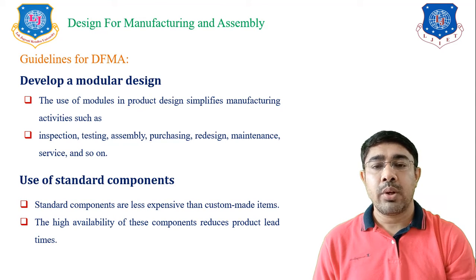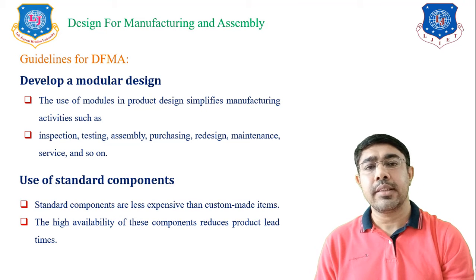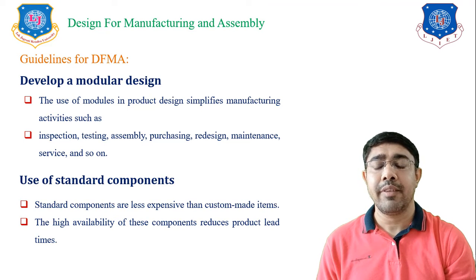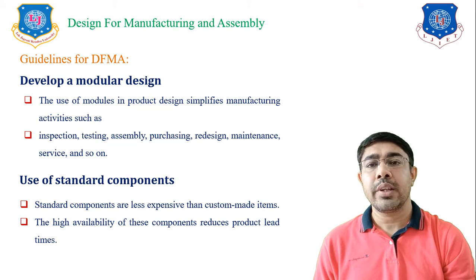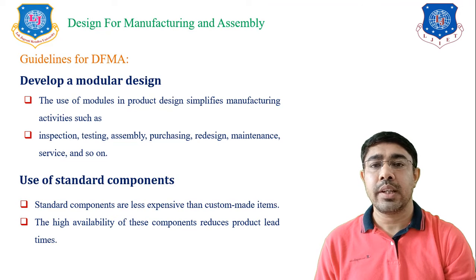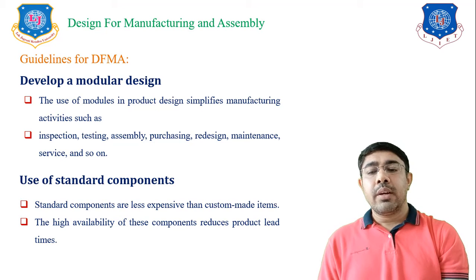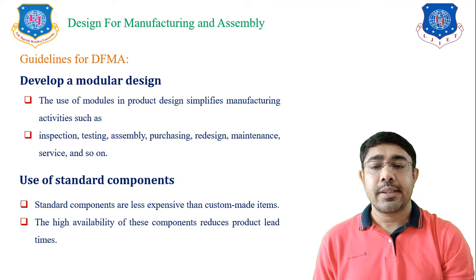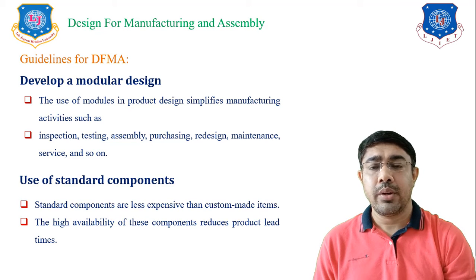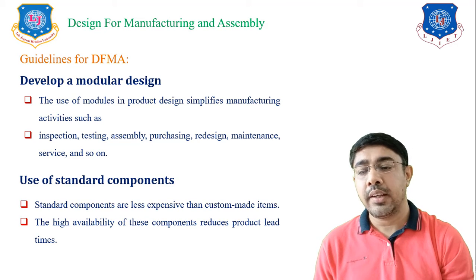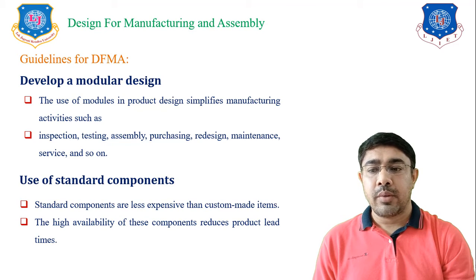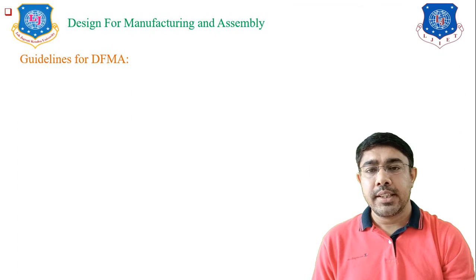So it will require more time, and also to make the custom components we need the process or the equipment, and we need time to make them. So it will increase the manufacturing cost and increase the product development or product manufacturing time. So we have to use standard components, which are less expensive as compared to custom components, and easily available in the market, so we can reduce the lead times of the particular components. So these are the guidelines for design for manufacturing and assembly.